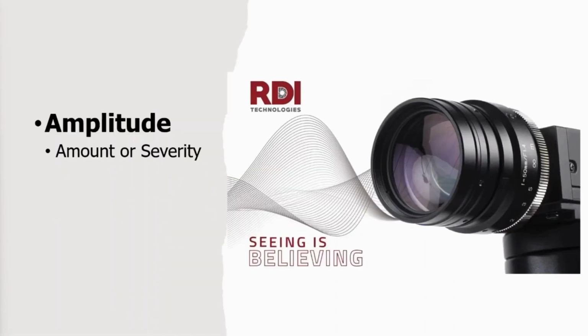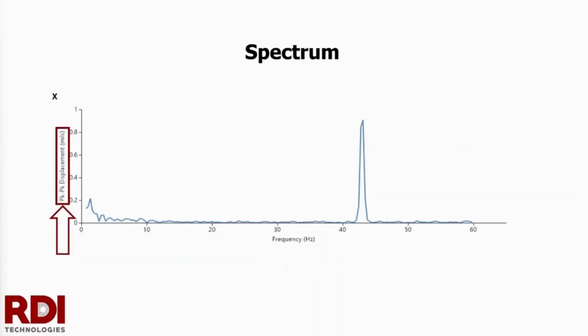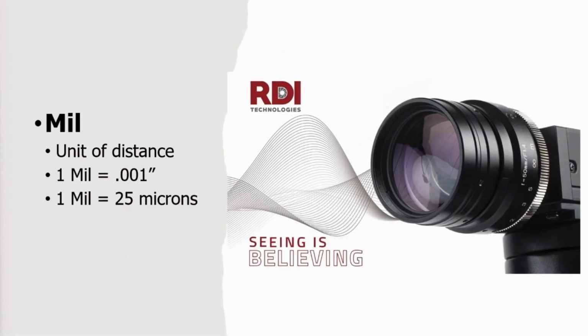Now, the amplitude is what we consider to be the amount, or very often the severity, of the vibration. And notice that on the left-hand side where we have that amplitude scale, the values say peak to peak displacement in mils. 1 mil is a unit of distance. It's 1/1000th of an inch. Or in the metric scale, we would use microns, where there are approximately 25 microns in 1 mil.